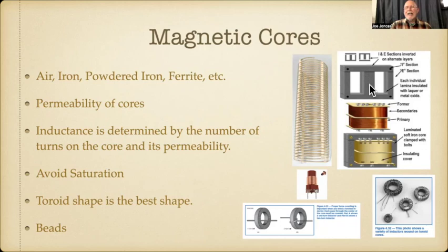it. And if you have a power transformer, you can actually induce some from this. But with this core, it's not too bad. And the same thing with this. With this core here, the field radiates outward. So if you had this here and then you had another one right next to it, they could interfere with each other. So if you're building something, you would have to put a shield in here to keep this one from affecting this one because of the magnetic field that goes out from it.